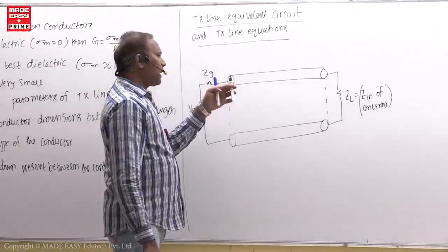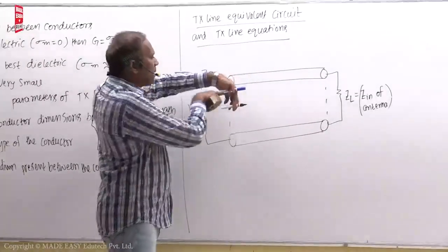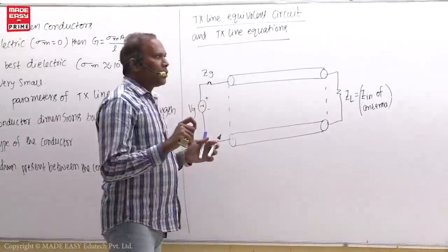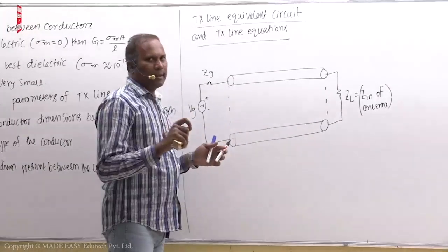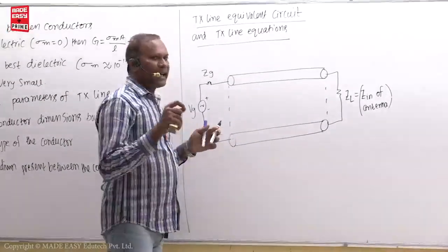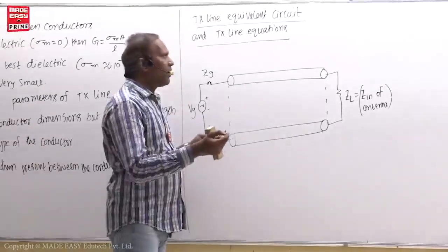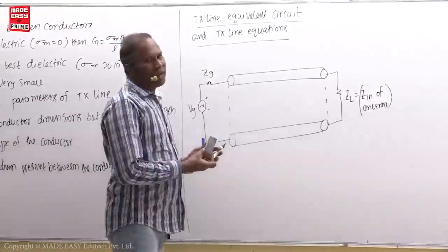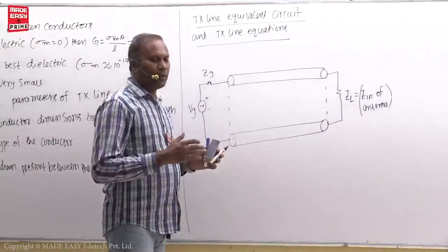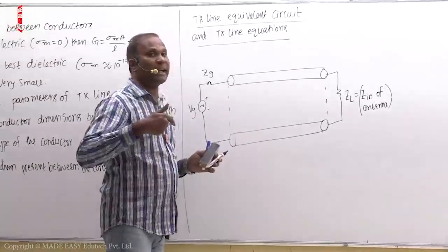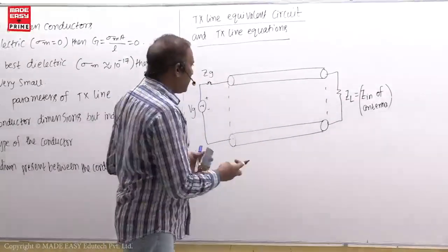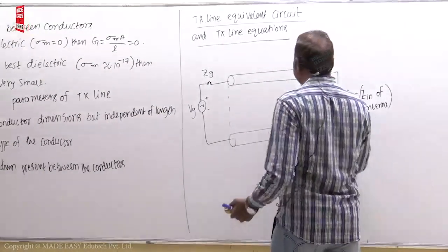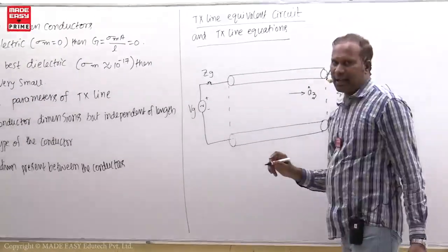Now even if we turn the conductors like this, we can take that as a Z direction, because I told you we always do the derivations and write the equations by assuming wave is traveling in Z direction. In the uniform plane wave also, in the transmission line also, in the waveguide chapter also. If wave travels in Z direction, you always get terms like e power minus j beta z like that. So let us take this is Z direction, az cap. Let us assume wave is traveling in Z direction.